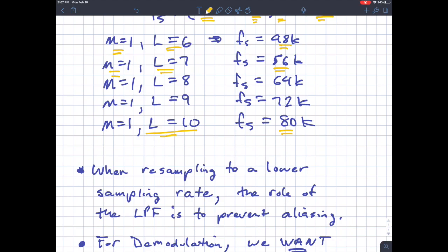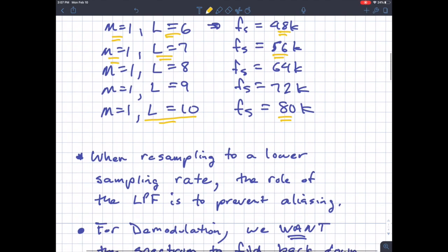That's going to be high enough for this discussion. You probably did something less than that, but you may have done an upsample factor of 10. We're going to talk about why you'll need to change whatever you did to land at Fs equals 80K. There's a technical reason we're going to need that sampling rate.